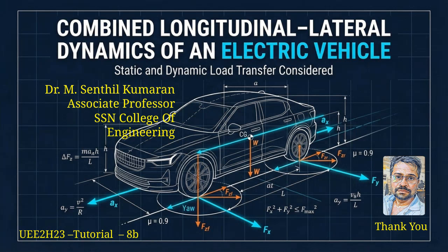As a result, the inside rear wheel becomes the limiting factor for traction. This leads to wheel slip, limits the effective rear axle force due to the open differential, and prevents the vehicle from maintaining the desired turn radius while accelerating. Vehicle stability, traction, and safe cornering performance are governed by load transfer and friction limits, with the least loaded driven wheel determining the maximum achievable performance.